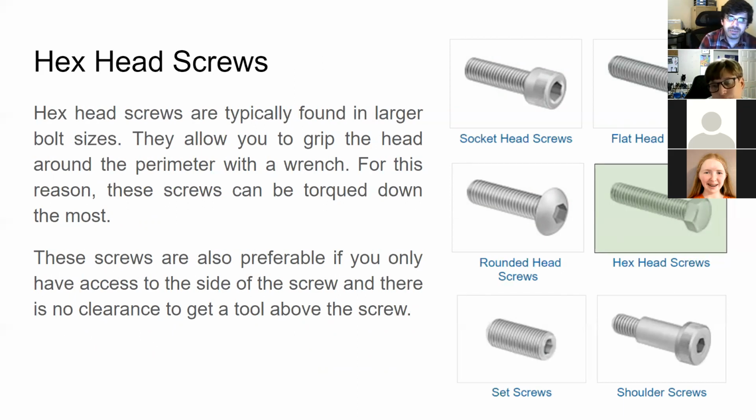We see these sometimes, like in the kit of parts, like drive axles are actually hex-headed screws. If you can't get your tool in axial to the screw itself, for whatever you're designing, the good thing about hex-headed screws is you're coming in out of plane, so perpendicular to the length of the screw. So you might have an application where that's the only style of head that would work.